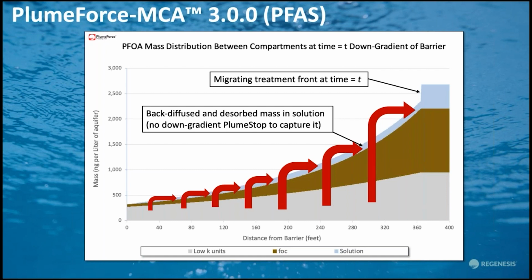Okay, modeling of 360 feet of heterogeneous aquifer is inappropriate on a practical level, but here the exercise is one of understanding rather than prediction. We can also see how in the zone to the left, closest to the barrier, the total matrix mass has already declined by some 90% and is continuing to clean up. The rest will follow in due course, and we can model and follow that. But importantly, we can see from the modeling what is going on.